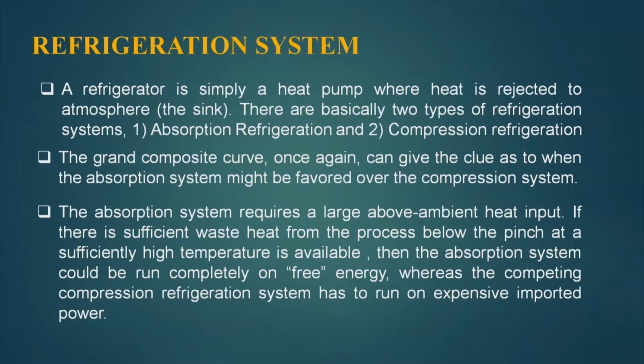The absorption system requires a large amount of above ambient heat input. Basically, for cooling in an absorption refrigeration system, we use heat as an input. That means the heat creates the cooling effect, and if a sufficient amount of heat is available in the process below the pinch at a sufficiently higher temperature, then the absorption refrigeration system can be run almost free of cost.